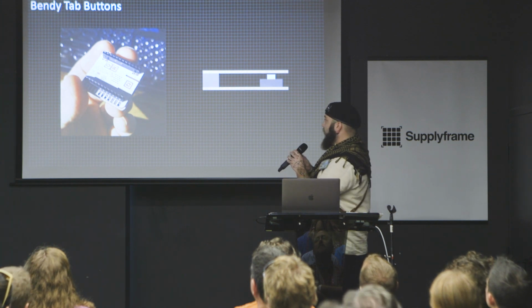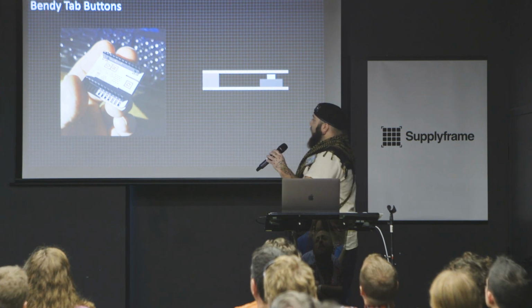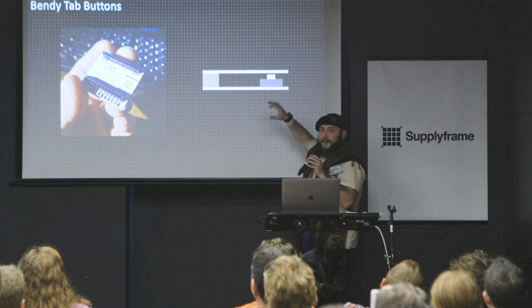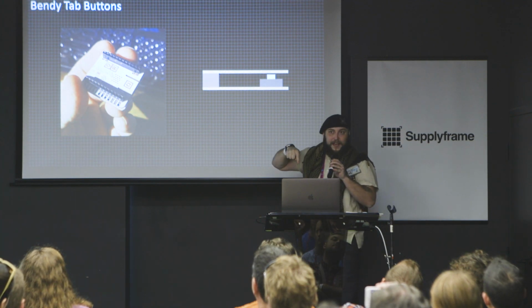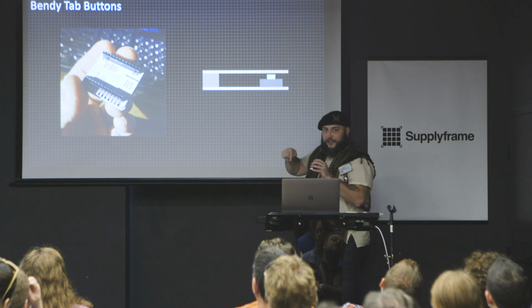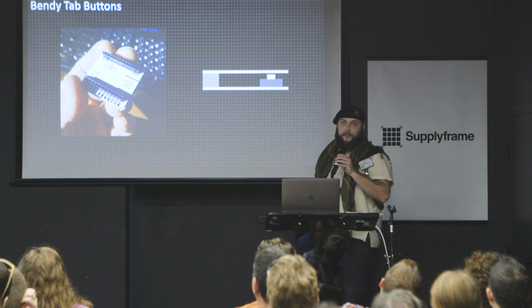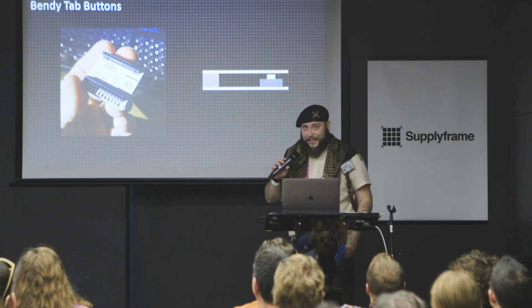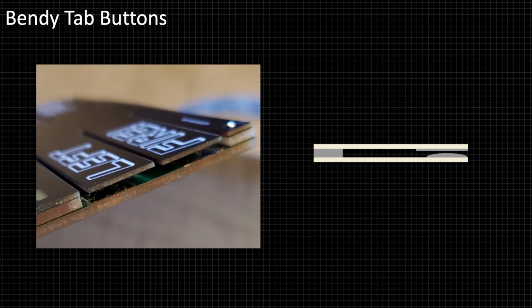So this is a little Arduino clone that I made that has the reset button as a little finger in the top sandwich of this PCB, and then underneath that I just soldered an existing push button module. This is nice because you don't need a lot of travel, so you don't need to push down on that fiberglass too hard and really flex it. You're just pushing down hard enough to hit that button, and you get the nice tactile feedback that's built into that button module. But if you want to be really cheap, you could just do this. This is what I did on the Space Invaders, the Cosmic Aggressors badge.